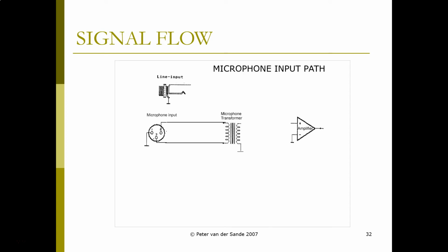We're going to take the output coil of the transformer and connect one side of it to ground, and then connect the other side of it to the preamplifier stage, which has its negative input also connected to ground. So to complete that circuit, we add the wire at the bottom, which just connects the two grounds together.